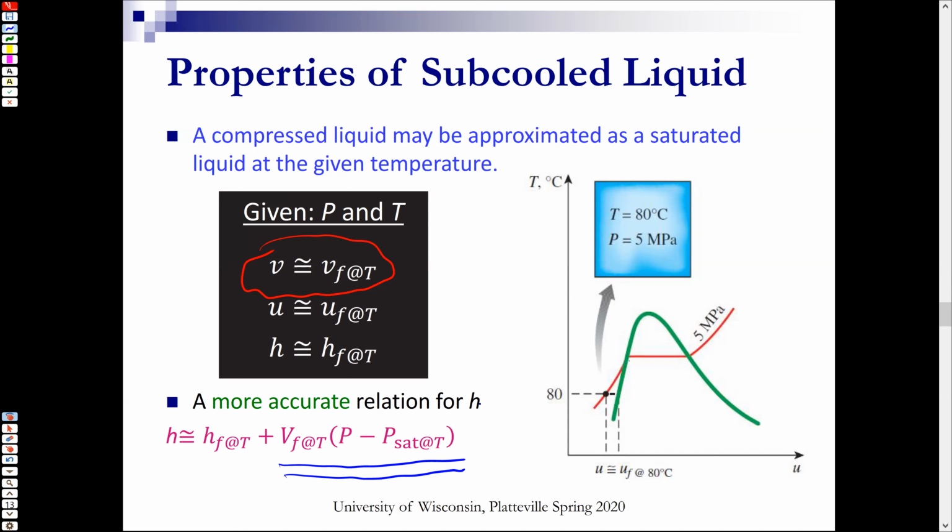Usually the second term is negligible compared to the first term, except for cases like pumps. In pumps and pumping devices, the second term is important because the change in pressure is important. We have huge changes in pressure in pumps, so this term is important there and we should consider it. But in most cases, we can neglect this term.